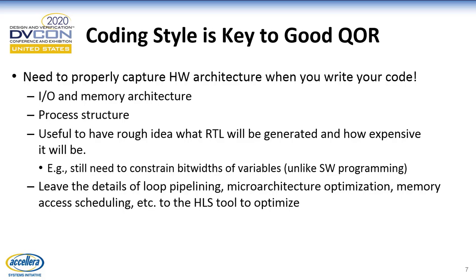So it's very useful, I'd say, that when people are using high-level synthesis tools, they should have a rough idea in their head of what RTL will be generated and how expensive it will be. For example, anybody using a high-level synthesis tool needs to know that multiply operations are expensive, and a 32-bit multiply operation is much more expensive than an 8-bit multiply operation. And you need to code your design up front with these considerations in mind. But you don't need to code your design all the way down to the level of Verilog RTL.